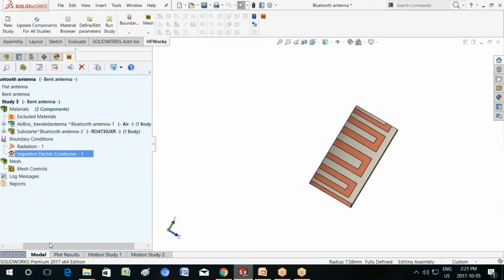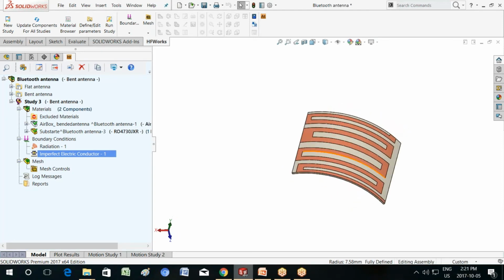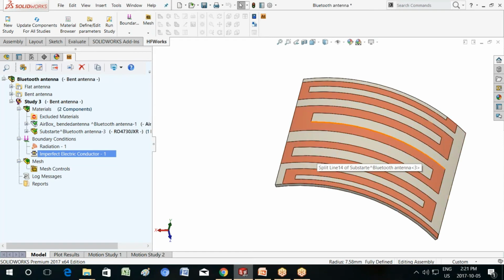And so this shows you how the process works on setting up materials, boundary conditions, and so on. One of the things I would like to show to illustrate some of the useful tools for antenna designers. Whenever you're working with structures that have metallic edges, and antennas at high frequency, you're going to have field concentration around the edges, and so meshing can take long if you wait for the program to do adaptive meshing and start with the mesh and keep refining.